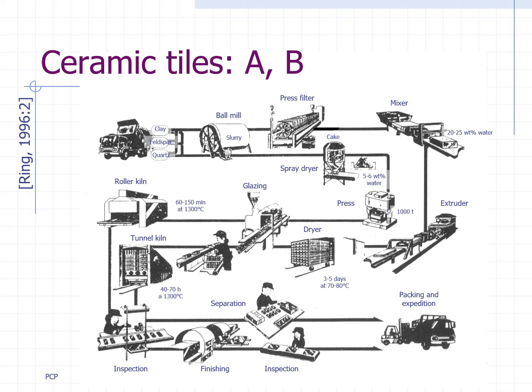In this case, the firing schedule takes 60 to 150 minutes to complete. Nowadays, sintering times of less than 30 minutes are normally used for ceramic tiles in modern plants. To finish, in any case, surface treatments, quality control operations, and packing and expedition are normally held in a ceramic manufacturing plant.